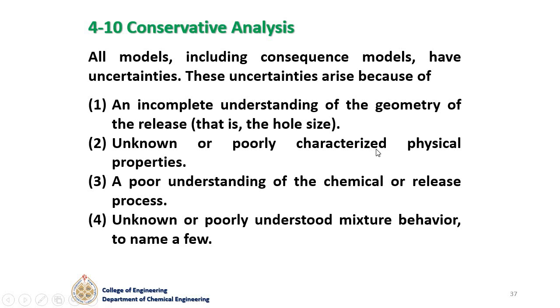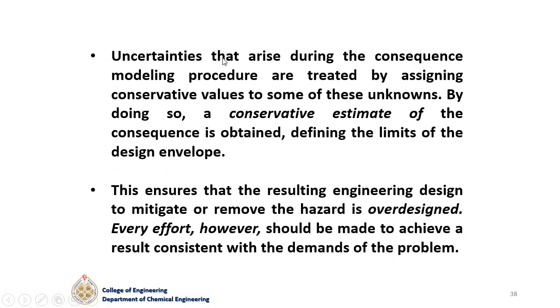Or I took some assumptions in the physical properties, or I have a poor understanding of the release of that chemical, that it's a new chemical for me. Or there's a mixture, and I did not understand how it will really disperse into the atmosphere. So there are many uncertainties, too many unknowns that we have. So the consequence that I'm expecting could be different, and my modeling procedure also depends on some assumptions.